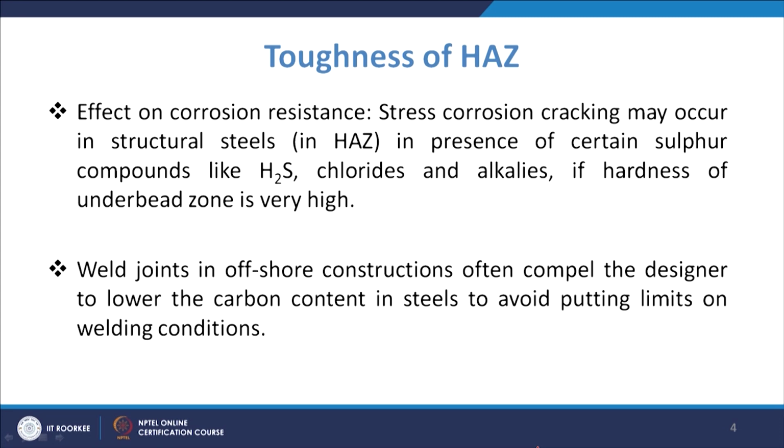What has been seen is that in offshore constructions many a times there is a compelling on the designer to lower the carbon content, because the hardness which is permitted is normally smaller. So, if you increase the hardness, that is going to affect the properties of the materials that may fail.